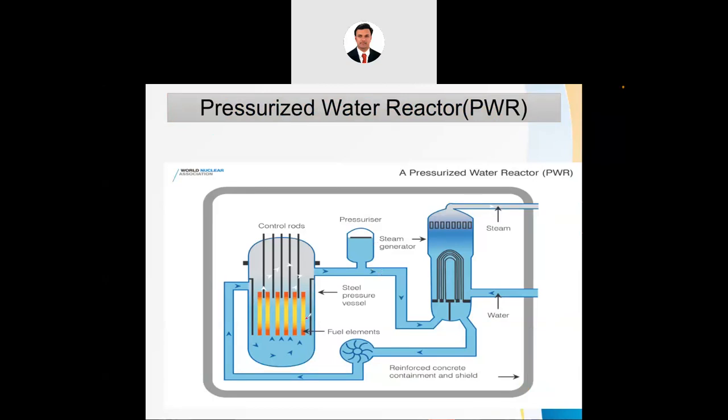Now here, the change is that instead of directly using the water that comes in contact with the nuclear rods, we cannot directly expand that water into the turbine. Instead, we pass this water through a heat exchanger. Here heat will be exchanged and given to the secondary cycle, or the second circuit of water.